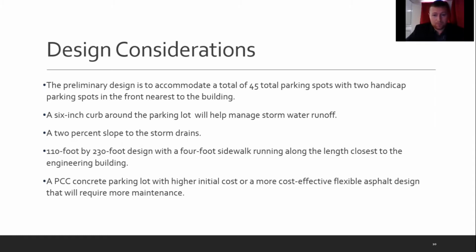Design considerations for both parking lots are that the total area is 110 foot by 230, so a little over 26,000 square feet. Both parking lots will have a 2% design slope and a 6-inch curb running around the parking lot to help manage storm runoff.